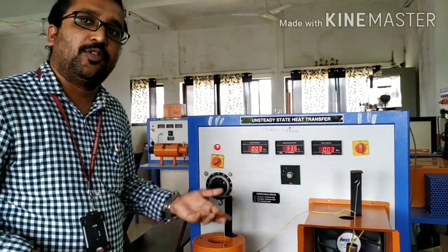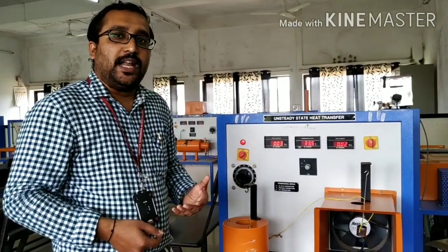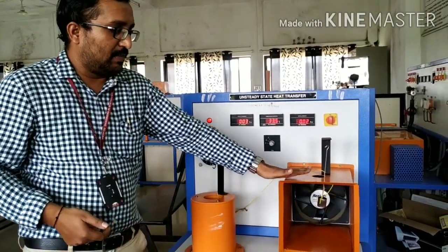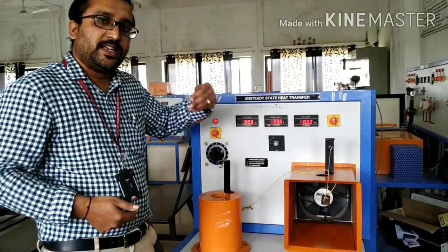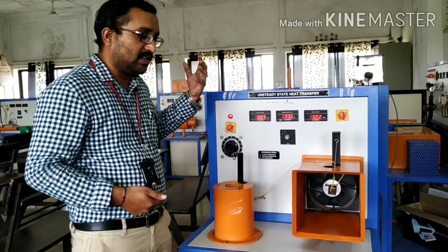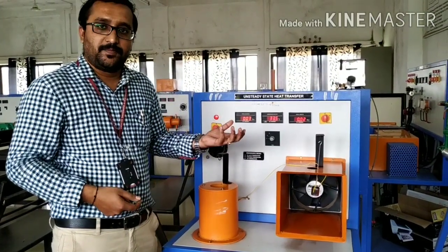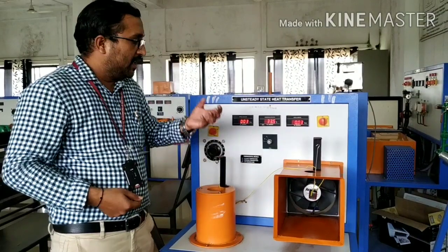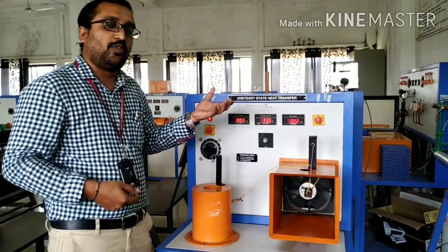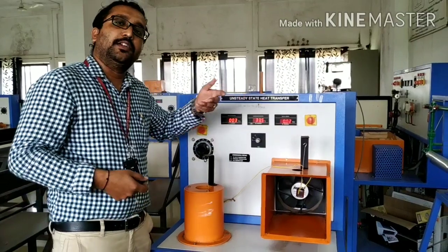If you want to calculate theoretically, we have a series of formulae, and using them we can very easily calculate. Since natural convection happens in heating and forced convection is supposed to happen in cooling, we shall use the same calculations we did in our previous labs for natural and forced convection. A similar kind of formula is used to calculate the heat transfer coefficient H. Once the H value is calculated, using the transient phenomenon and a mode of analysis called lumped system analysis, we shall calculate the temperature of the specimen at any given interval of time.